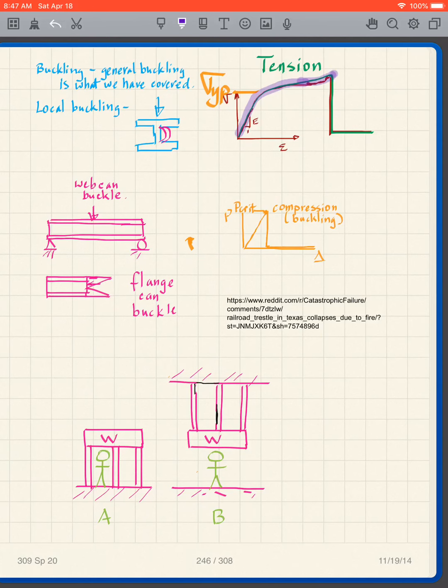Now, typically, the way that you see these curves drawn is you get an X there, meaning you have fracture. Well, if you look at it in a slightly different way, you load, and you're getting more resistance, more resistance. Then what happens, you get fracture, and then it takes no more stress, but you get a lot more strain. So another way to draw the stress-strain curve would be something on that order.